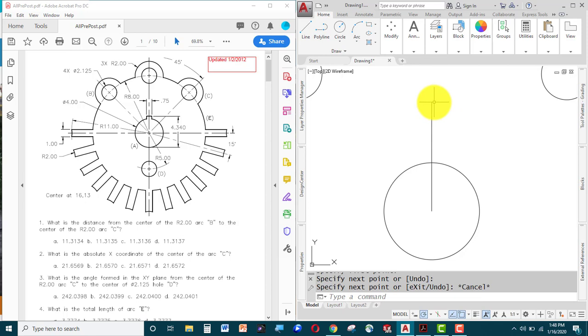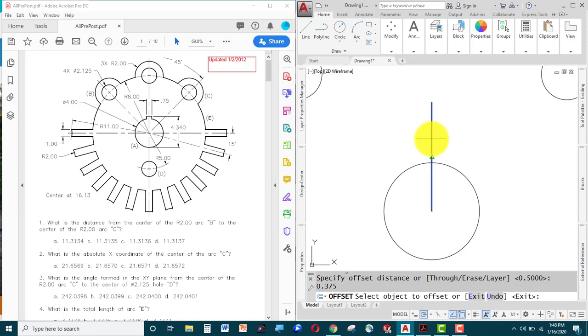Now this keyway width is 0.75. You know and I know that 0.75 divided by 2 is 0.375. So don't do that. Instead, even though this one actually is a simple one to do, when you go to the offset command, you can type an apostrophe, CAL, enter. That'll give you a transparent command. Apostrophe means transparent command. The calculator can be used while you're in another command. Now I type 0.75 divided by 2, and I don't need to worry that I make a mistake in doing the math. When I do that, it returns 0.375, but it also uses that with the command I'm in.